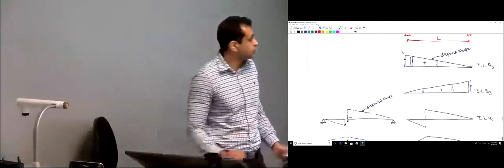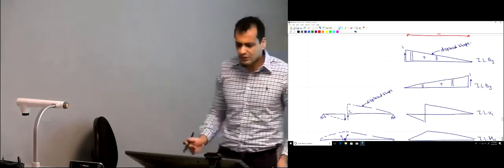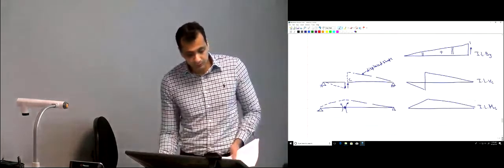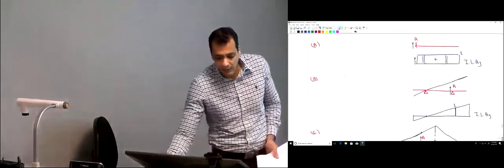For the shear, which is two forces, this is the shear force. So you just come here at C, you displace the beam like this, and that's the displaced shape, and the shape of the displaced shape is the shape of the influence line. For a moment, you introduce a hinge here, and then you put a unit moment, or a unit rotation. Moment is two rotations like this, and then it displaces like this, and this is the shape of the influence line as well. And then we took this example. I'm not going to go through it.